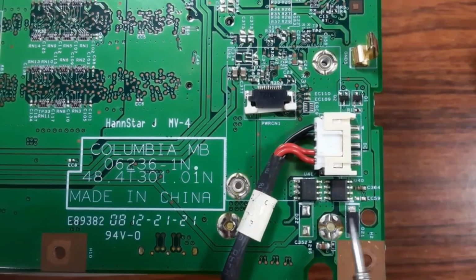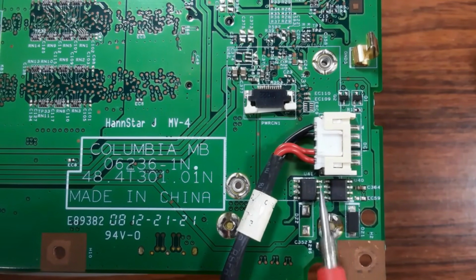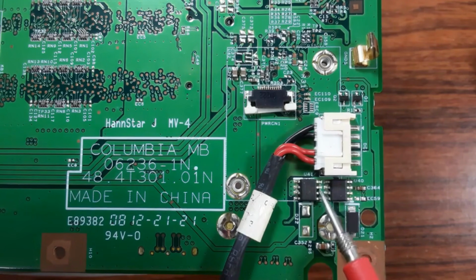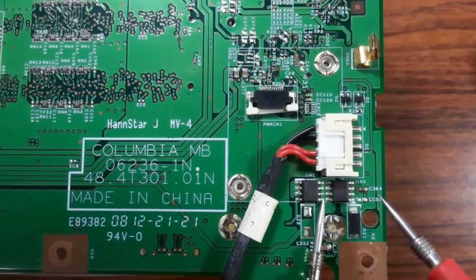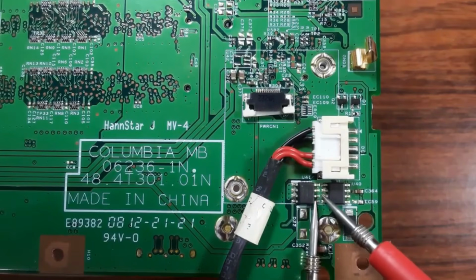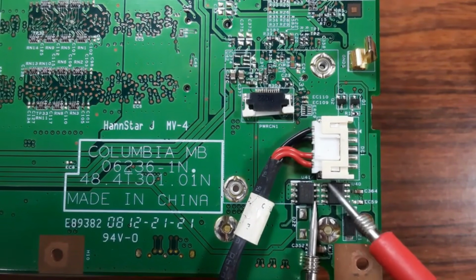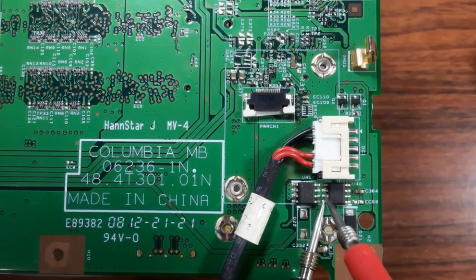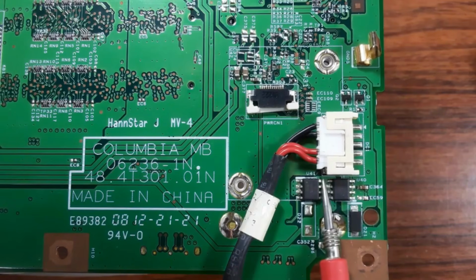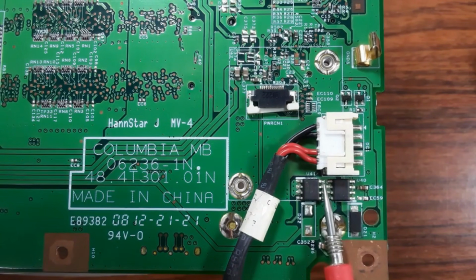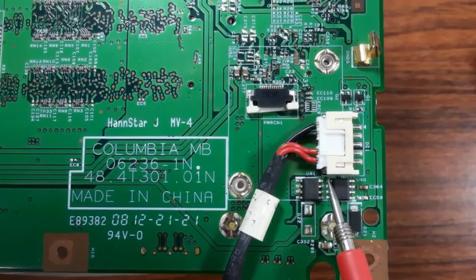Then here, if you focus, we have the drain. This is the drain because all these 4 pins are connected together, and also here we have the drain because these 4 pins are connected together. So let's check these pins: the second, the third, the fourth. Also these pins, the second, the third, the fourth. And all these 4 pins are connected to this. Why? Because here we have the same color, the green color. All these 4 pins and these 4 pins are connected to this green color. Means this is the same path.